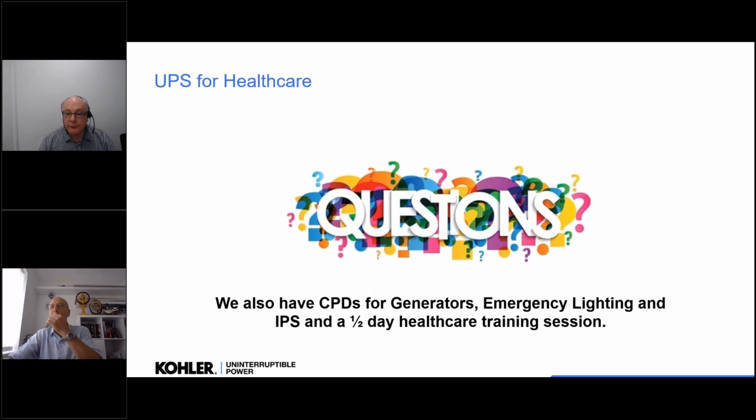One attendee has asked, do cooler temperatures reduce the battery efficiency the same way that hotter temperatures do? Temperature is very critical on batteries. We size batteries at 20 degrees because that's what we say you should run them at for maximum life.